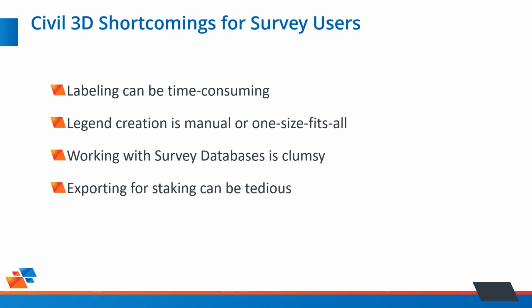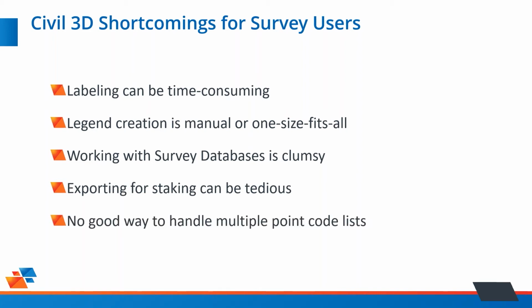Taking design data and exporting this for staking purposes can be quite tedious. Think about multiple code lists. A lot of organizations out there have multiple code lists. Perhaps the surveyor is surveying on Monday in one code list and another day in another code list. This gets pretty tricky to manage, and so that's another challenge. And then finally, standards management, like your description key sets and layers in your Civil 3D templates, can be time consuming as well.